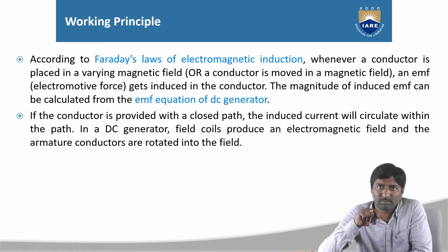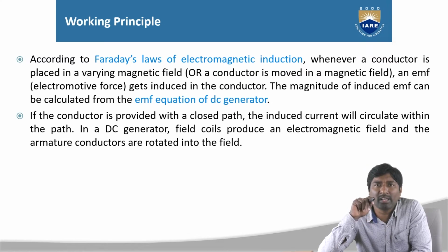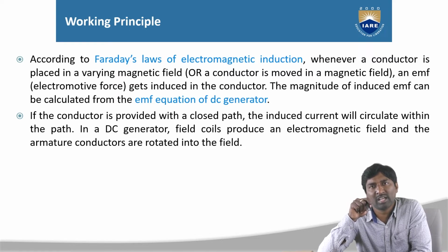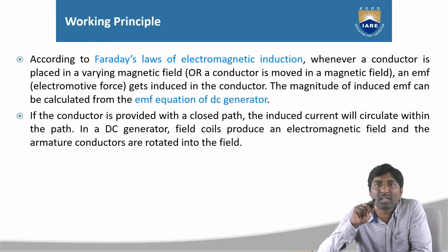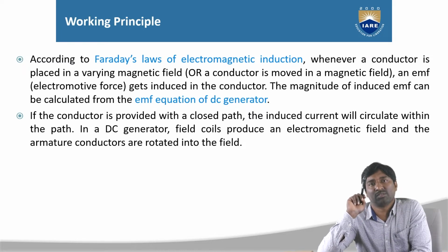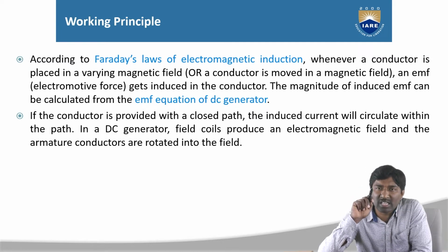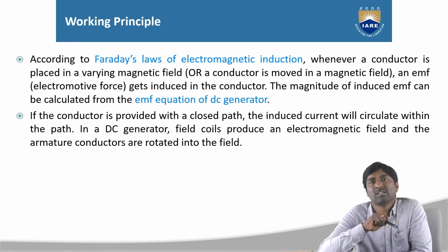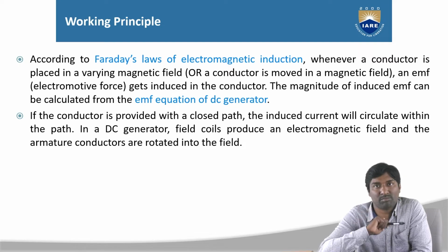If the magnetic field is rotating and the conductor is constant, then also the induction process is there between the conductor and the magnetic field. Then we are getting the induced EMF. That induced EMF I am calling a statically induced EMF. So in case of the DC generator, the principle depends on the dynamically induced EMF.